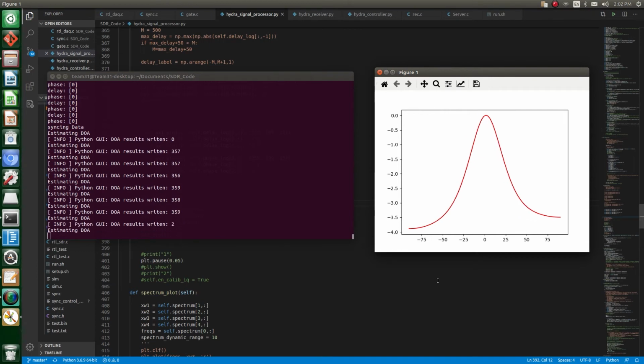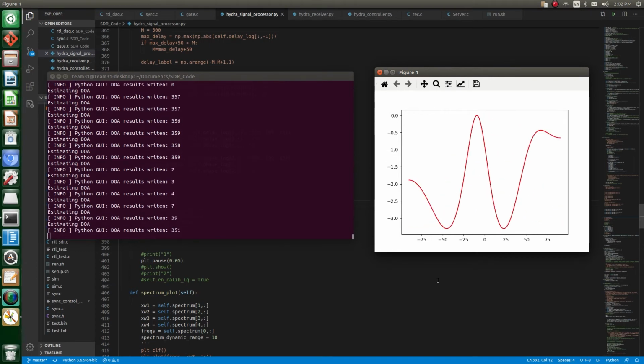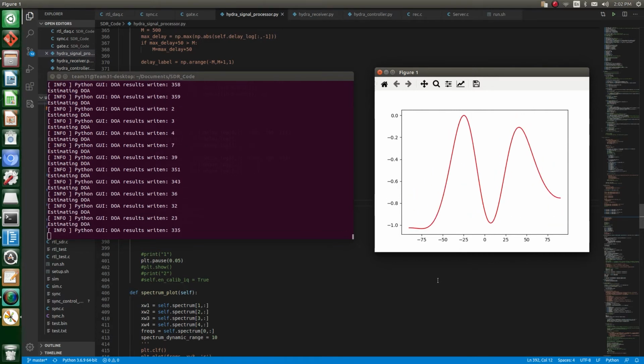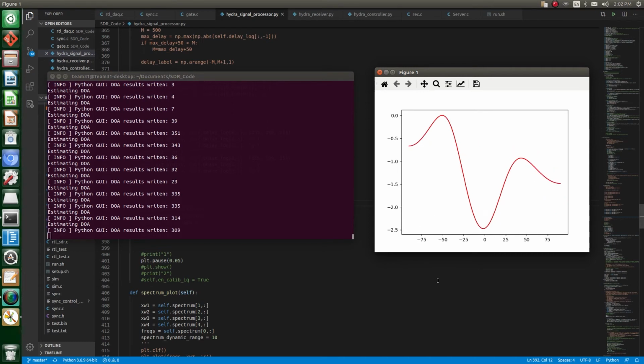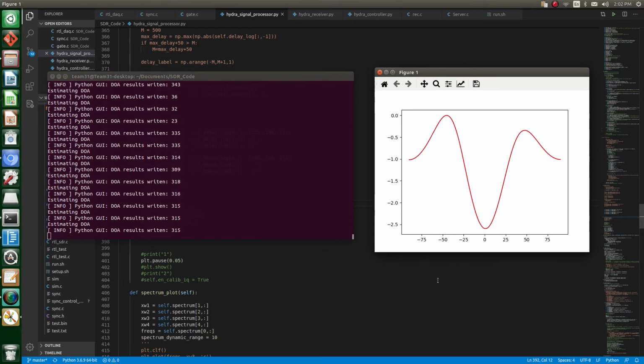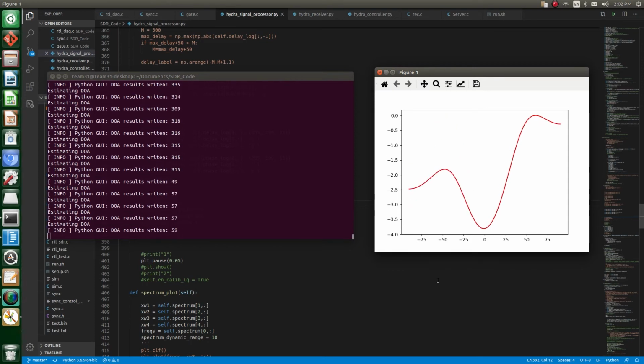The phase delays are calibrated with each of the antennas removed so that each individual element seen from the Kerberos is the exact same. Later, when the antennas are attached, the Kerberos will then be able to see the phase difference of incoming signals due to the spacing of each element. Calibration uses an internal coded noise source, which is turned off once everything is successfully synchronized.